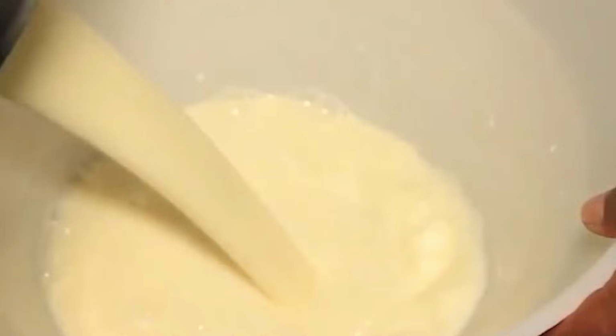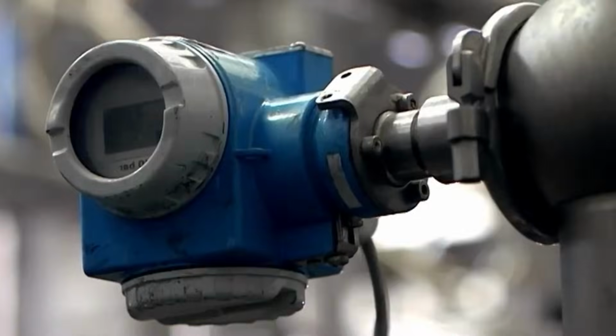These industrial freezers use scraped surface barrel designs, where the yogurt base is frozen while being continuously agitated by rotating blades. The barrel wall is chilled to between -20 and -30 degrees using ammonia or freon-based refrigeration systems.